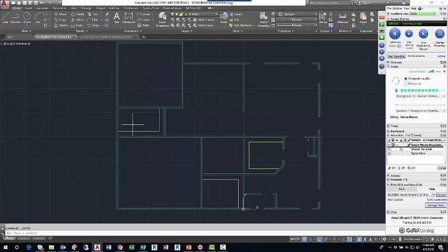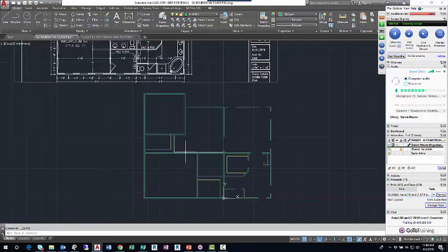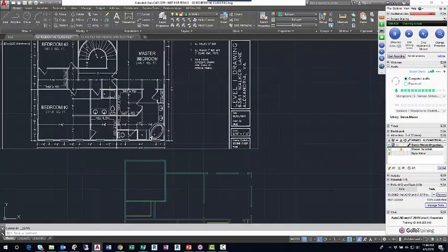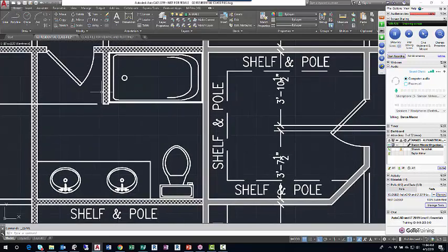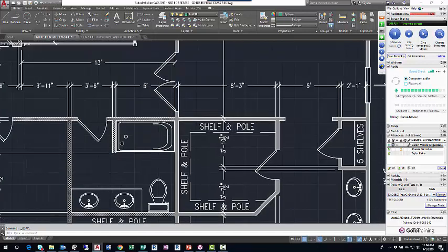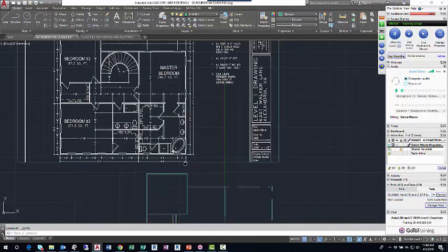Okay, so still a lot of offset and trim, right? I did an offset for the shelf lines. There's a little wet wall that sits in front of that tub in the hallway. That's just an offset of 5 feet from the left line of the master bedroom wall.